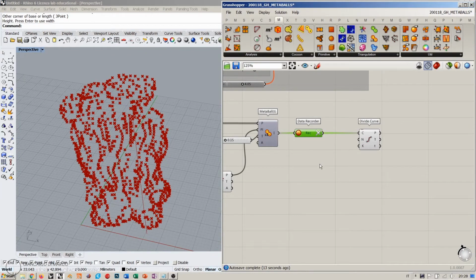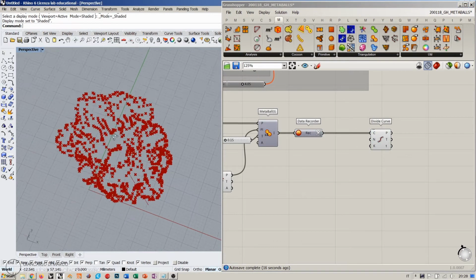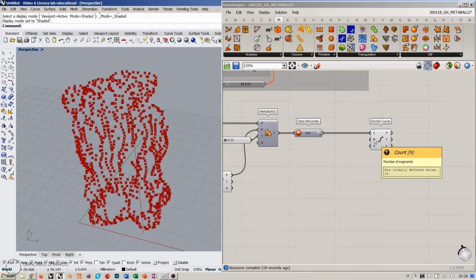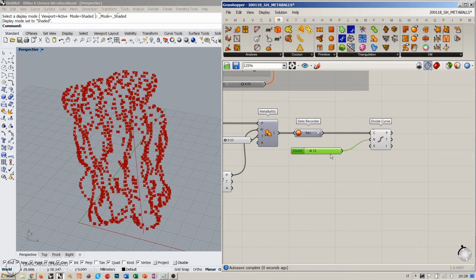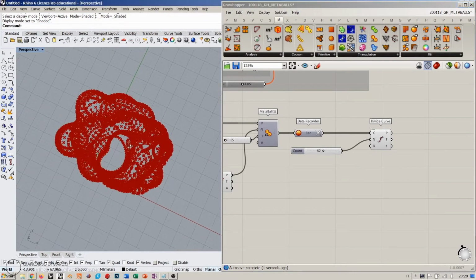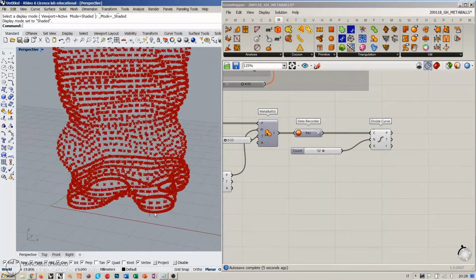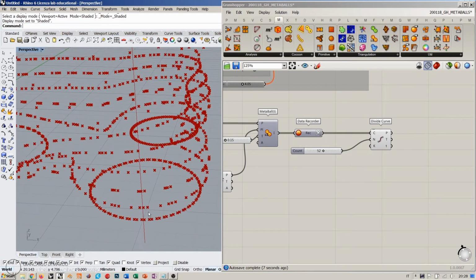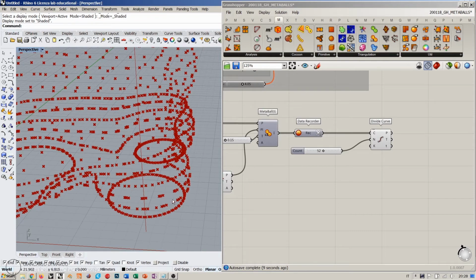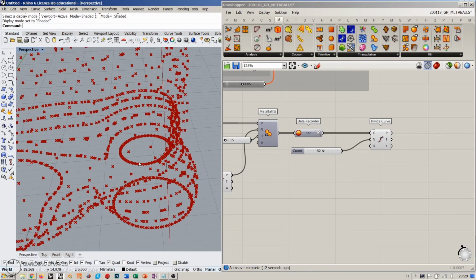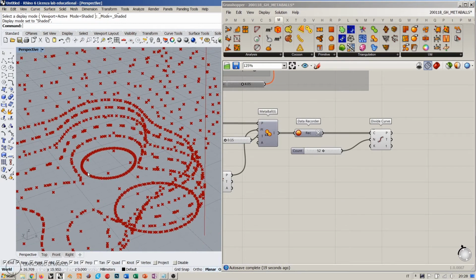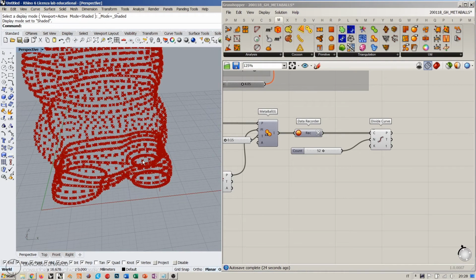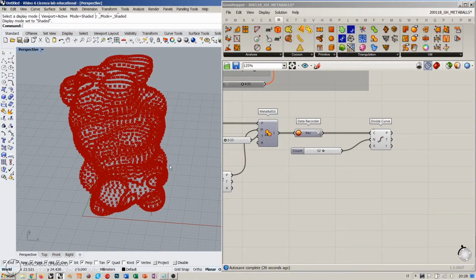Eventually what happens here, and this is not evident in this moment, but if I start to increase the amount of segments here, for example with a 11 slider, I notice that the Metaball curves that are shorter generate a more dense set of points, of course. So you see that all these curves here are being divided into 52 segments, okay? But this set of points is way more dense than this set of points. This is because our curves have a different length.